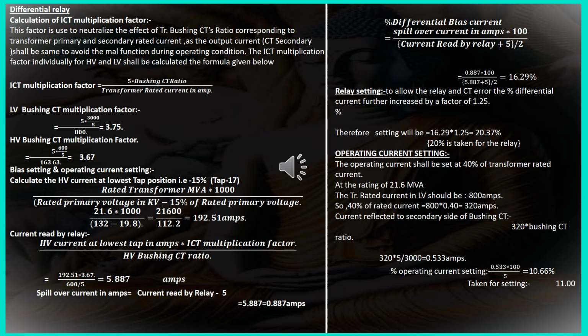And then if any change is there, suppose your feeding zone has increased, a siding has come, at that time you have to set your relay setting again. So you should know it, because to call the company again it is expensive. So better to know something about it.